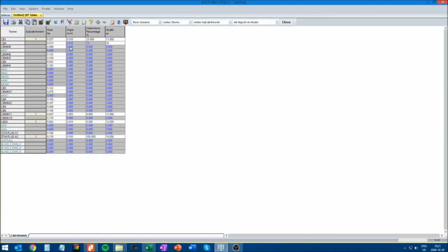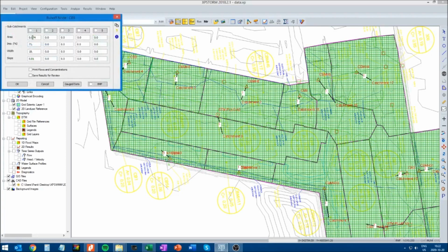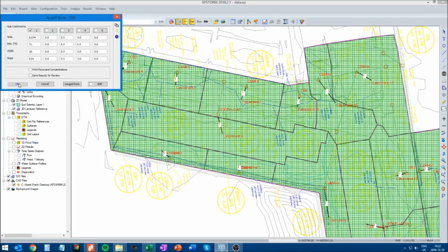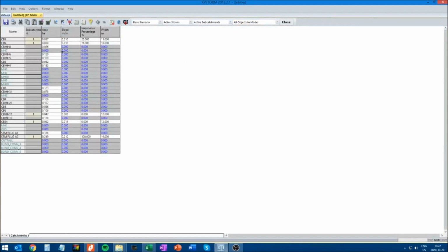And I'm going to do the same thing with all the other subcatchments, and then I guess I'll have to go back and manually add the 1 into each catchment. The way to do that is I'm going to close this. So for example, here, left click, right click, edit data, and just click the 1, go OK for now. We'll set the parameters later and go OK. So back to the table, and we can populate all these other values.